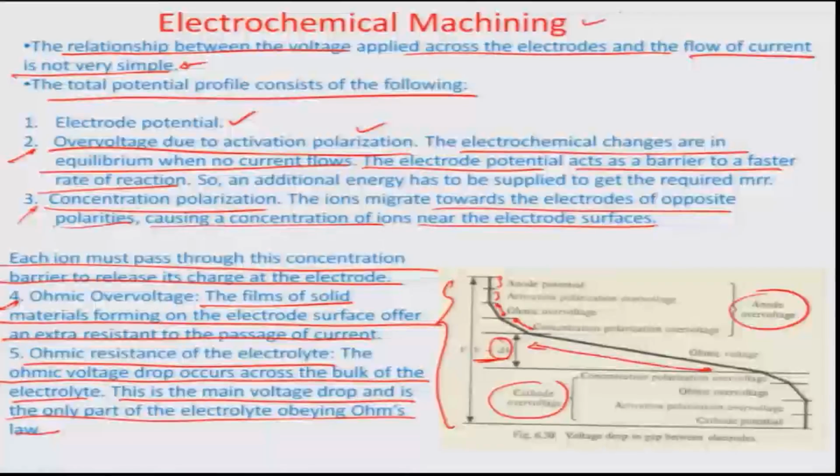So while doing electrochemical machining, you have to always obey the fundamental rule that there has to be not only the redox potential at which the dissolution will start to happen because of the oxidation reaction, the reduction reaction taking place simultaneously, but also you have to consider that in order to reach that potential point, you have to cross several barrier layers, and therefore a slight amount of extra voltage needs to be provided for such barriers to be crossed over, so that you are exactly at that point where oxidation reduction can happen within the electrochemical machining apparatus.